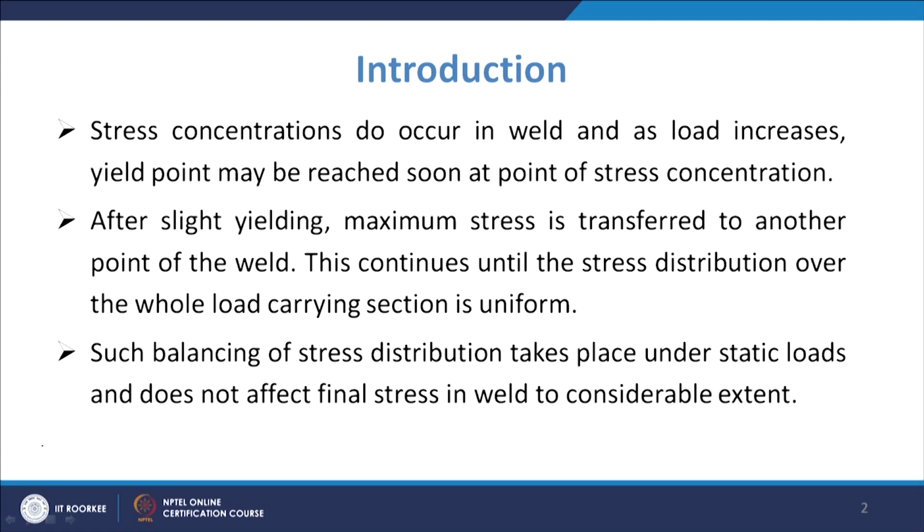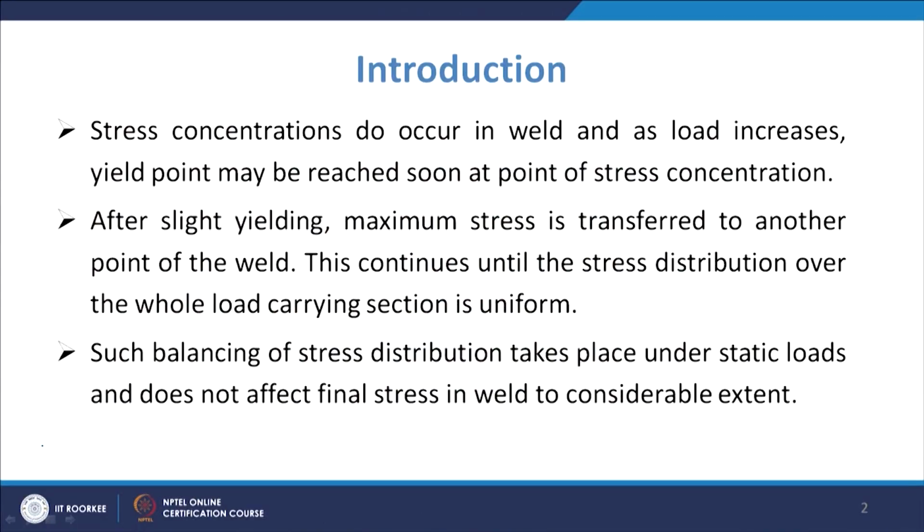When the yield point is reached, there will be small yielding, and then after slight yielding, this maximum stress will be transferred to another point of the weld, where another stress concentration is achieved and the stress value will be more than the limit. So this continues until the stress distribution over the whole load carrying section is uniform.